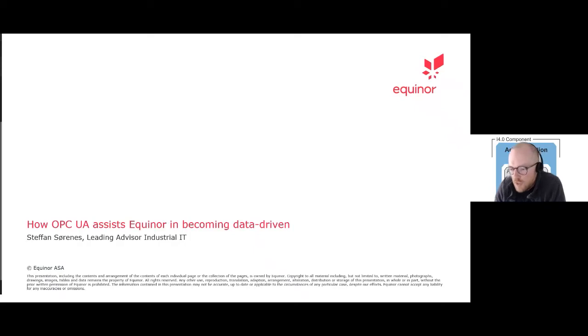Yeah, so in OPC UA, you have two communication models. You have a client-server communication model, which is the original one, the default one. In the client-server communication model, you can subscribe to data by exception, or you can pull the data. Part number 14 is a second communication model, which is pub-sub, where the OPC UA publisher publishing data is decoupled from the subscribers subscribing to the data.